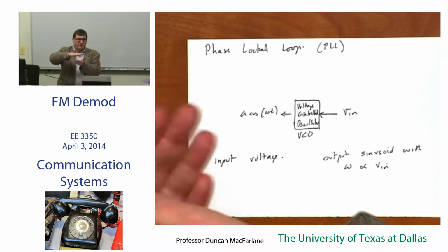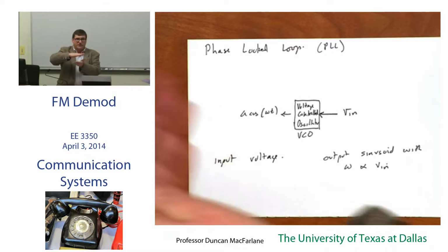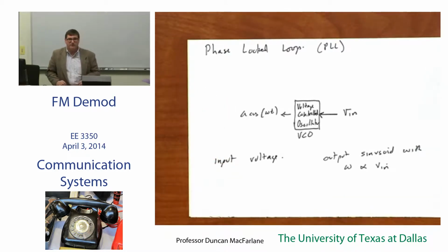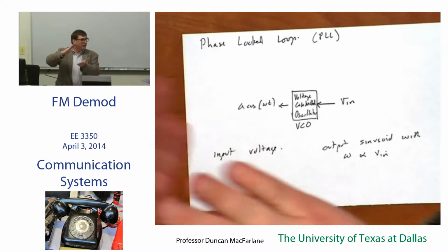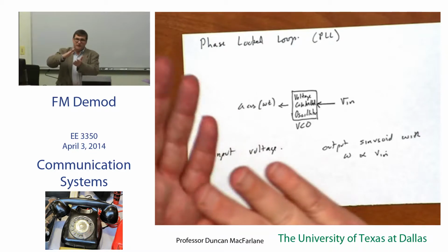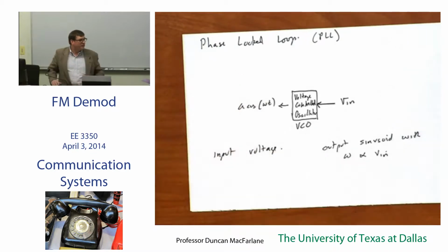So if I change K or I change M, I'll change the frequency of the oscillation of that spring-mass system. So if I can do that with a voltage, that's the piezoelectric effect, then I can tune this oscillation. And quartz is a nice PZT crystal, so you can make this thing fairly cheaply, and the technology has grown up impressively over the years.